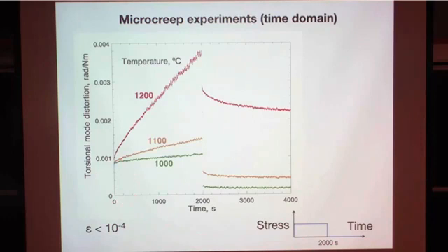The first thing here, we have instantaneous. So this is a measure of strain. Don't worry about the exact, this is just the fact that we have a cylindrical geometry here. That's just strain on this axis. So on application of a step function stress, we have an immediate response. And the immediate response, if you think way back at the beginning, that's Hooke's law, right? So if you compress a spring, you have immediate compression. So we have directly here elastic behavior.